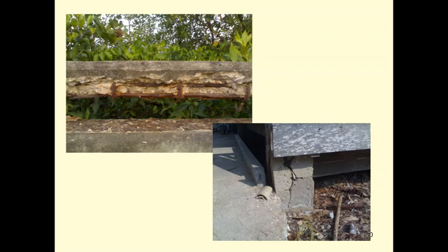And what is that? It is the covering. When you design the concrete, usually you have the section of the beam or the column like this, and if you build this structure in the seashore area, this covering must be especially larger than the normal one.